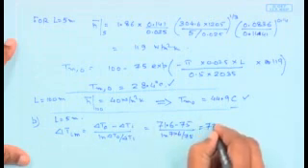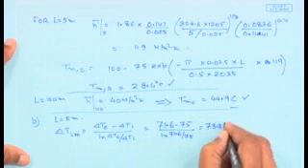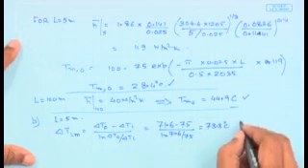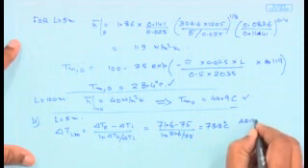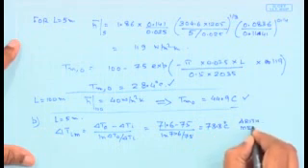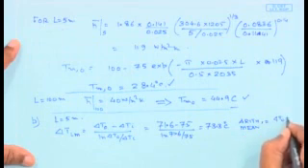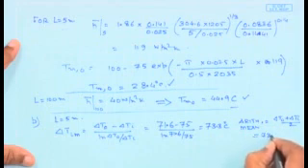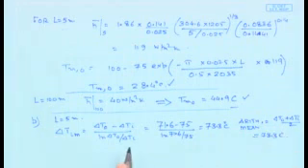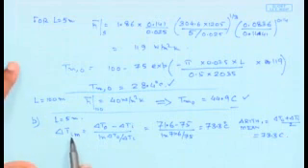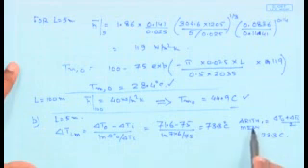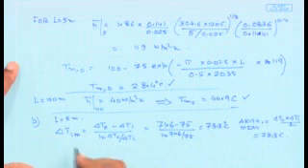So you would see this turn out to be 73.3 degrees centigrade, and if you do the arithmetic mean, which would simply be delta T outlet plus delta T inlet by 2, this is also going to be 73.3 centigrade. So for a short length, we don't see much of any difference between the log mean temperature difference and the arithmetic mean temperature difference. Both are equal to 73.